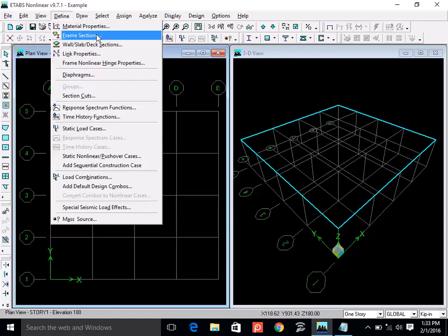Okay, so I can define some beams 9 inches wide or 12 inches wide by 15 inches deep, or maybe 18 inches deep. This is the minimum requirement for deflection. The formulas in ACI for the spans of the beams are the minimum requirements. You have to go sometimes beyond that. Okay, so I will define my beams as